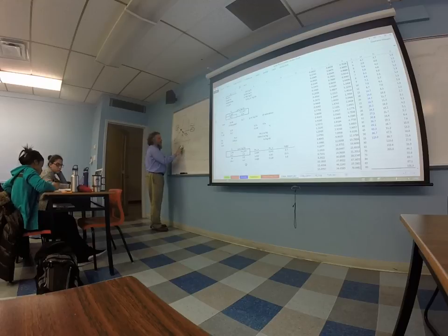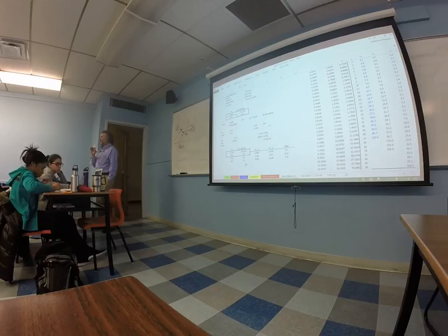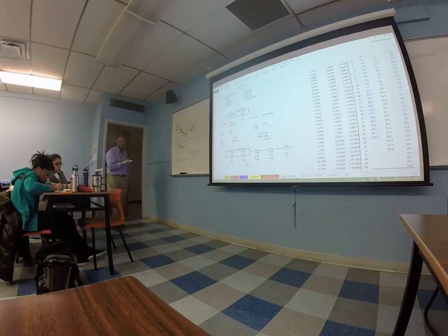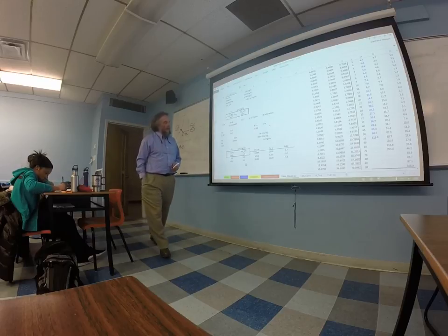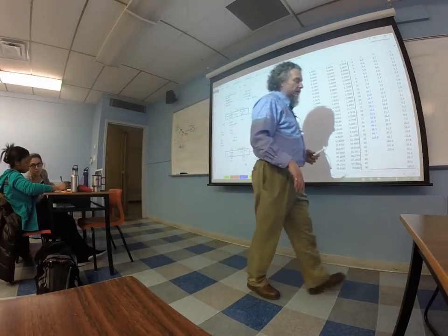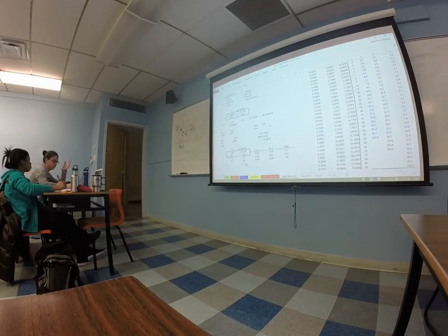Once I have enthalpy, I can calculate the temperature of saturation, because the moisture content at saturation depends on the temperature. So at saturation, I only have one variable for the enthalpy. What we do is calculate this, although it's recursive, it could be done algebraically.